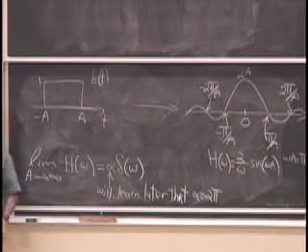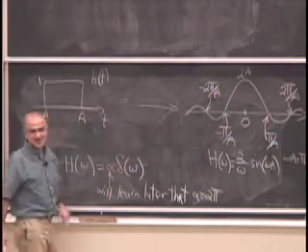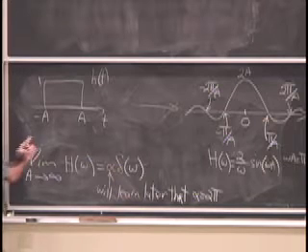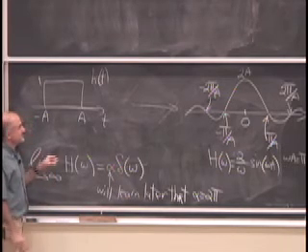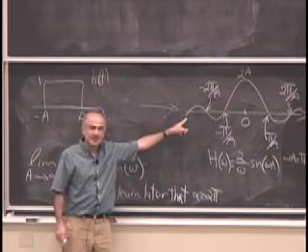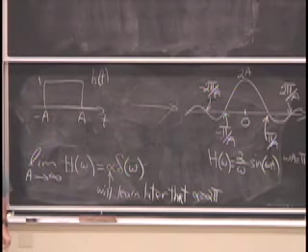No, it's not the ideal low pass. The ideal low pass would be a sinc in the time domain and a box in the frequency domain. This is the box in the time domain and a sinc in the frequency domain. You're not equipped yet to do the other situation. Because if I had given you this kind of a function in the time domain, you can't plug it into that integral because it won't converge. So there are some shenanigans that happen.